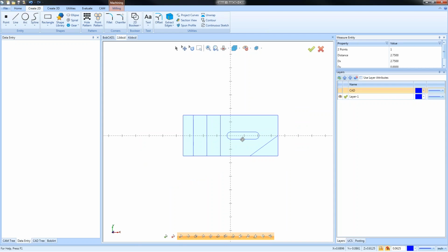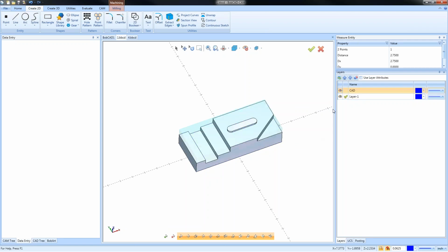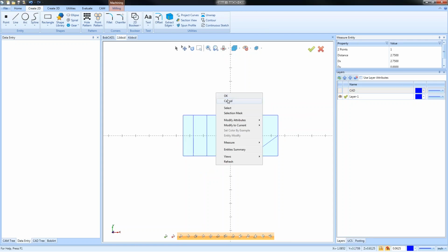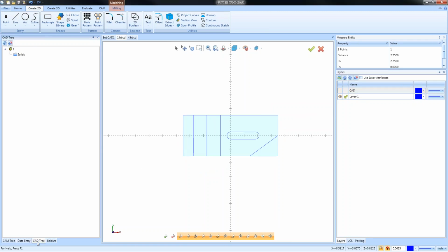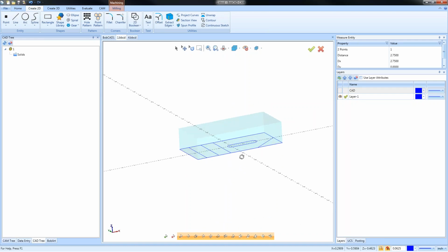You'll notice, Tony, every time I create wireframe, I always create a new layer and make it active first. The reason why I do this is it makes it really easy to separate out or to isolate your geometry. So you can pick or turn off the solid and just work with the wireframe. Okay. Now, if you're working with the wireframe, again, because I extracted the wireframe, you may get a print in that's just wireframe like this.